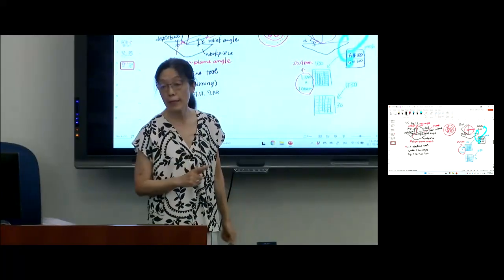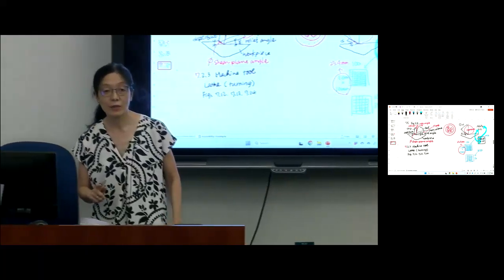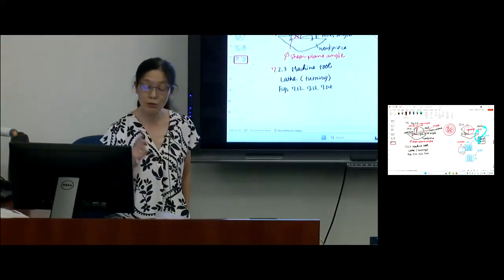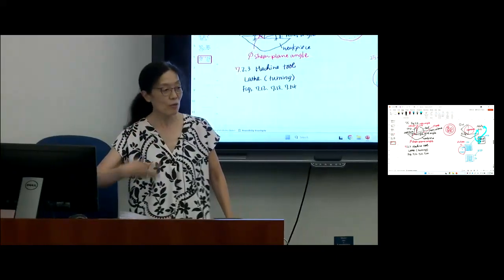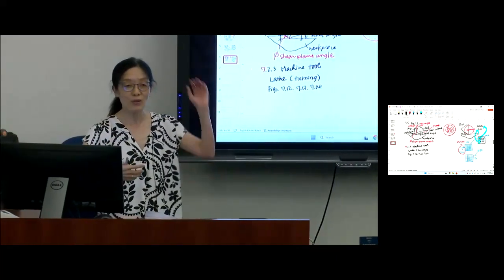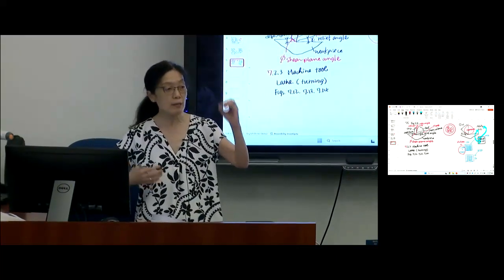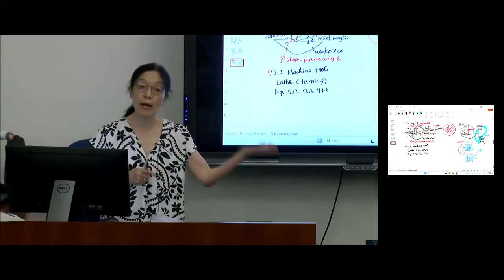So before you operate, make sure where the machine stop is. This is not only for lathes, but on a lathe it's sometimes hidden. That's why I'm kind of insisting. Because you use modern machine tools, right? So you always have a red button, but you don't know once you go out.